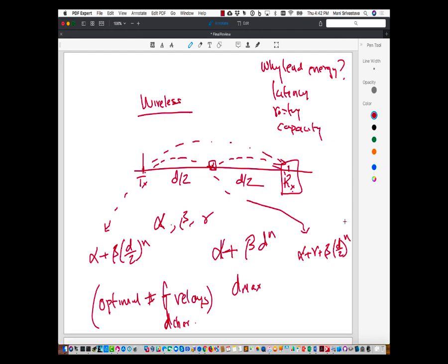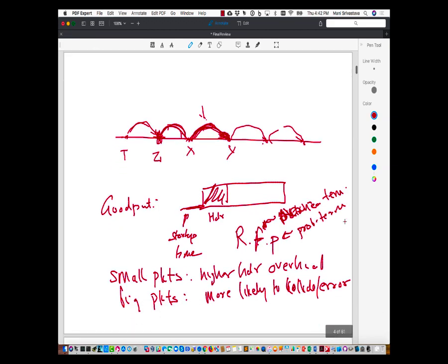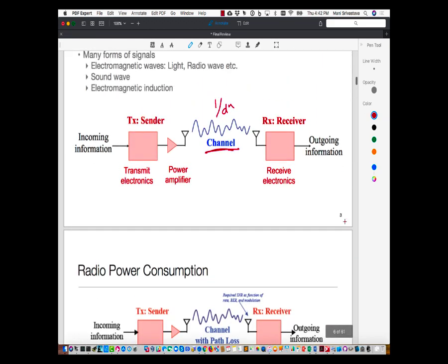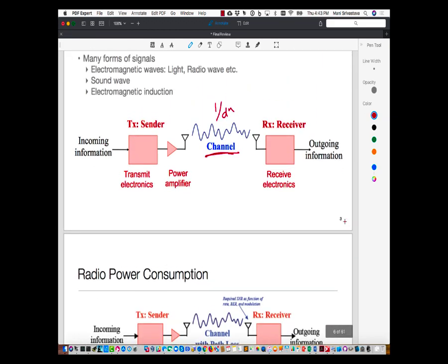So one of the other points which I had alluded to during the main lecture, that these amplifiers, remember, their efficiency matters a lot. Now it turns out that some of the modulation schemes which pump a lot of data through that high capacity, they also require amplifiers which have good linearity characteristics, and therefore they are less efficient. So when you're thinking about these things, it's kind of a complicated co-design of multiple things going on.